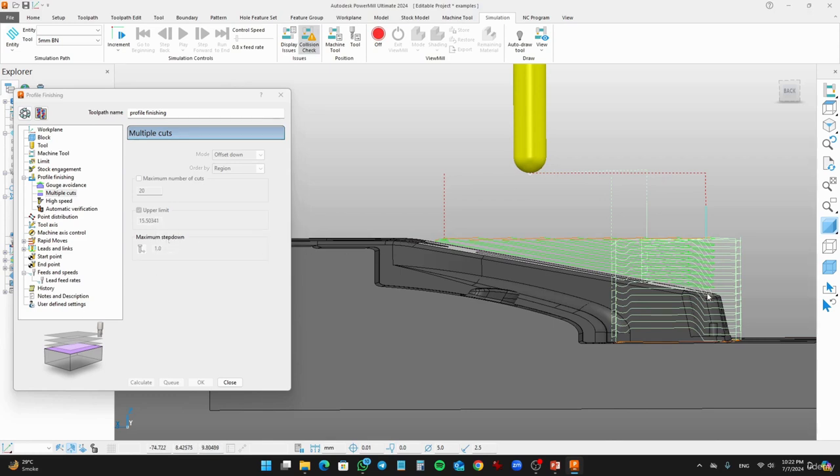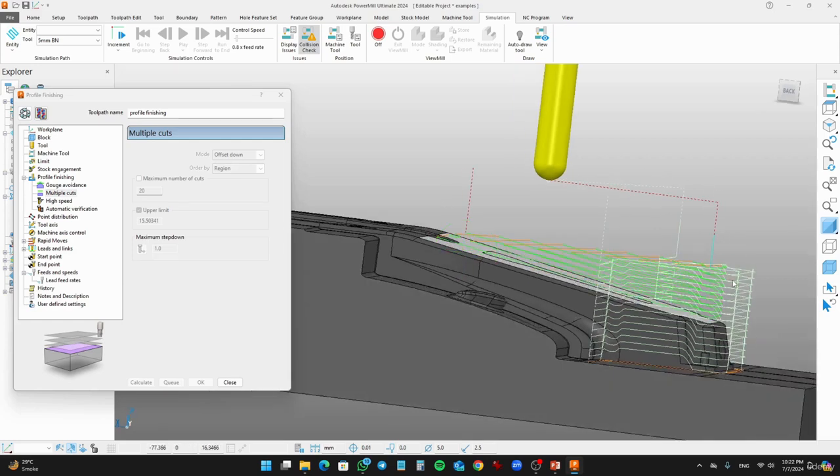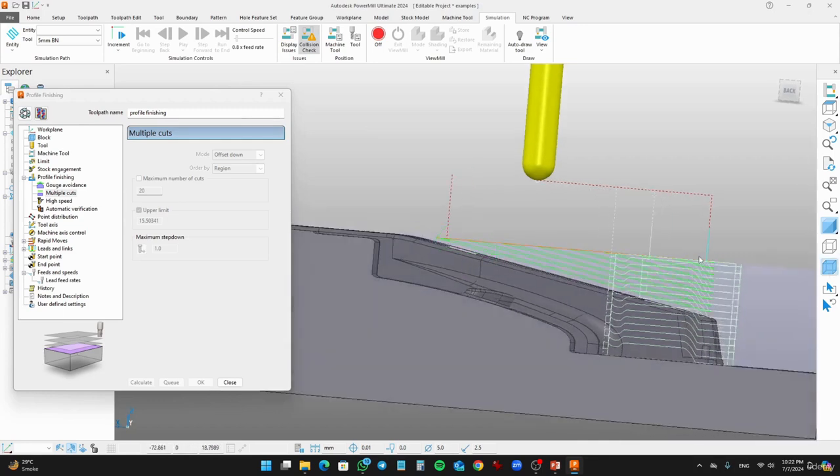The distance from this point to this point is not 15 millimeter, it's 15.5 millimeters. But I just give an upper limit that the maximum material present here is 15 millimeter. It is controlled by calculating the stock material we have up to this point. So give a random value, give the maximum step down and calculate it.